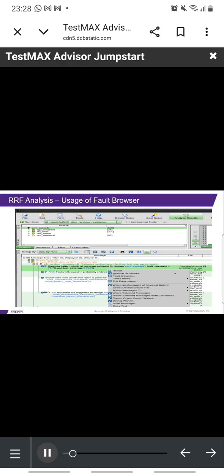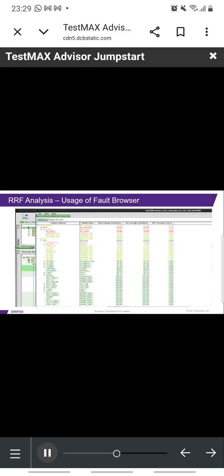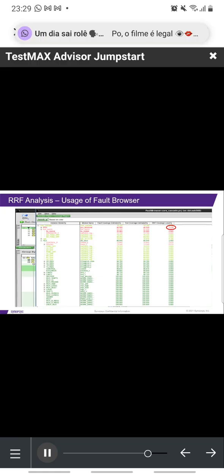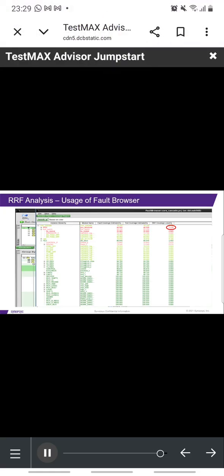After random resistant fault analysis is run, fault browser can be opened from info random resistance rule. You will need to select the message under info random resistance rule, right-click on it and select fault browser option. The fault browser helps to analyze the distribution of hard-to-test faults for different hierarchies in the design. The hierarchy contributing to the maximum loss in random pattern coverage for the design can be noted from this report, and it is also possible to dive deeper into the hierarchies.